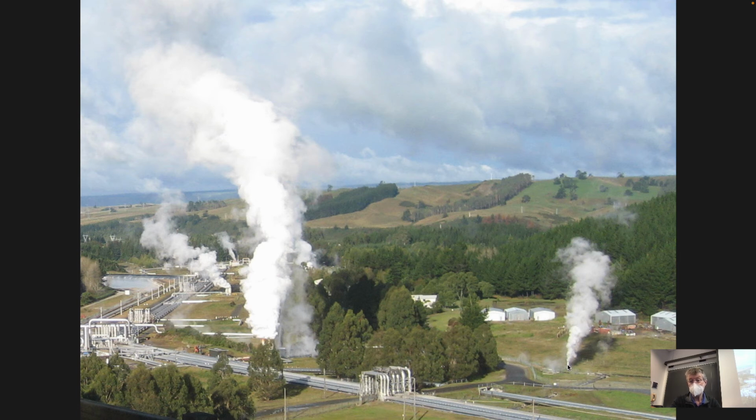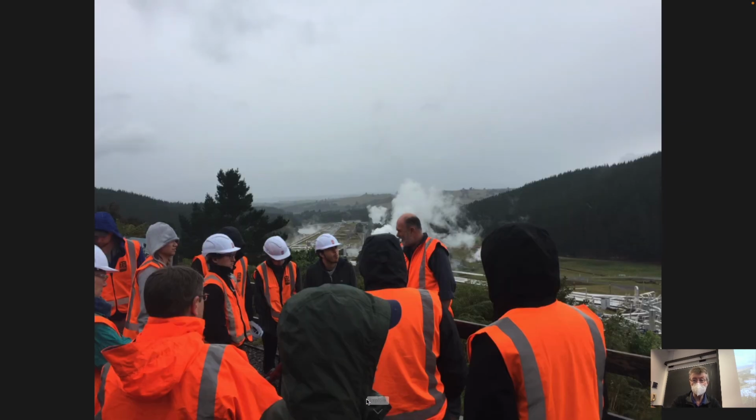Here's a wellhead that's off-gassing here, and they go all the way up the valley. They're on rollers so that they can thermally expand or contract. Where they go across roadways, you have them arched so they can also take up the thermal expansion and contraction, and you can also drive underneath them to get from one side to the other, just as a way of being able to both accommodate the thermal expansion in the pipes and also be able to have roads that go underneath these regions.